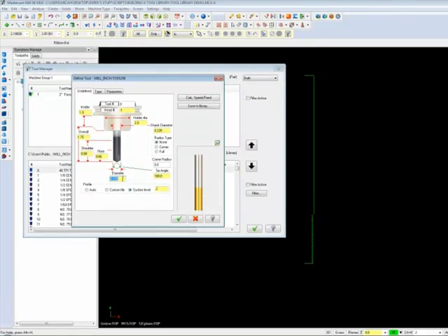So yes, that absolutely has to be the correct value, and yes, the threads per inch are important as well, really for verification purposes at this point. So the tool diameter is going to be very critical to your G-code output, because obviously you need the right diameter end mill for the radius offset calculations that go out to the machine. Drawing the pitch on the screen, the pitch has to be correct as the feed rate.